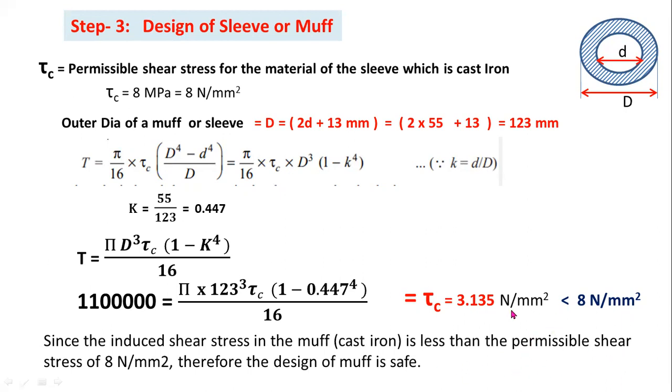Since the induced shear stress in the muff is less than the permissible shear stress of 8 megapascal, therefore the design of muff or sleeve is safe. So this is the design procedure of a sleeve or muff coupling.